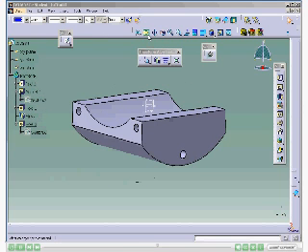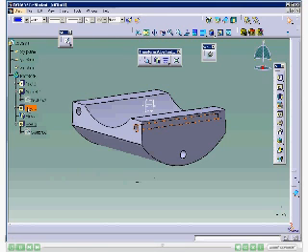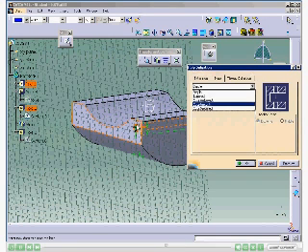After creating the model, you need to perform some editing operations on it. The first editing operation is to replace simple holes placed on the front face of the base feature with the countersunk holes. Double-click on the right hole placed on the front face of the base feature of the model. The Hole Definition dialog box is displayed. Now select the Countersunk option from the drop-down list provided in the Type tab of the Hole Definition dialog box. Invoke the Type tab of the Hole Definition dialog box if it is not already selected.